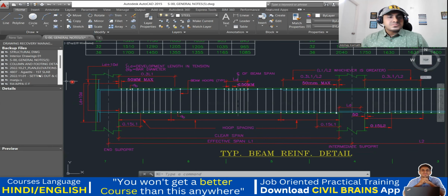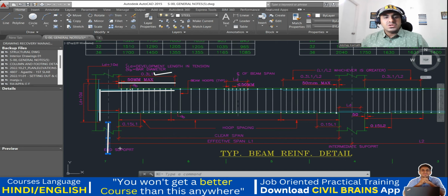After that, what is left out? After that, you can see the top extra bar. This is your top left extra. You can see this bar. This is your top left extra bar, isn't it? So from the face of the column, how much it has to be extended is mentioned here. It has to be extended up to 0.3 into L1. What is L1? L1 is your effective span.